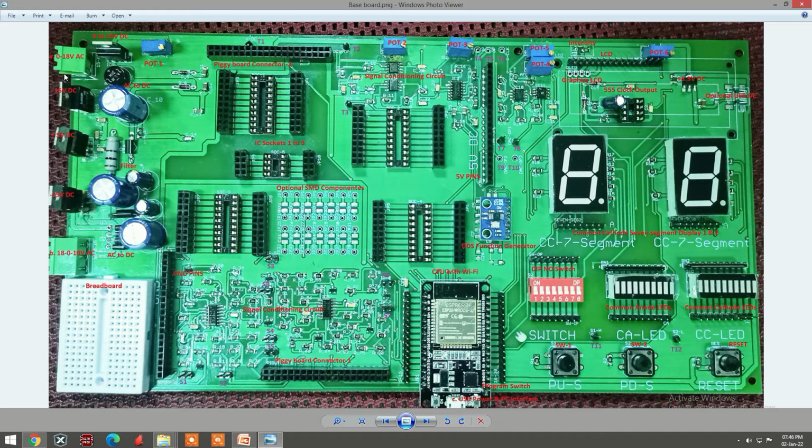Also, since the input is AC, you need to convert it into DC first before filtering. As you can see, there is a rectifier. There is a bridge rectifier here, and there is another bridge rectifier here, using the diodes, right? So as you can see, this entire section is called the power supply section. As good as we have replaced the traditional heavyweight power supply by using these components. Okay, so that's the source for that.